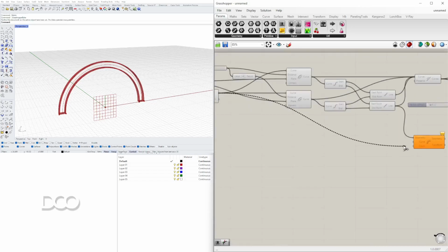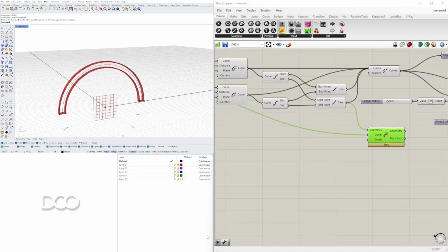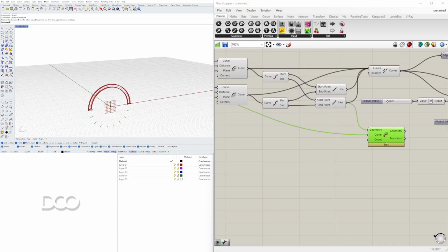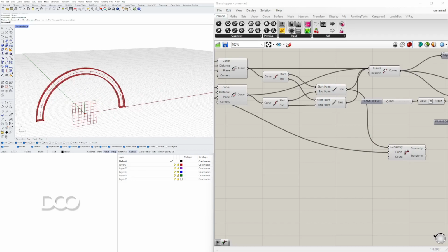this arc as a curve, and you'll see that we should do the other side because the curve is the other way around. So this one is the one that will actually work, right? If we select this is the start, this is the end, it's going to array it this way. If you have it organized all the way around, then it's probably because of the way that the arc is created, you have it backwards.